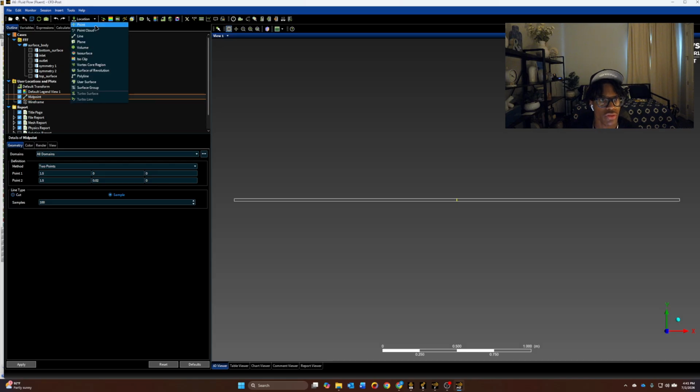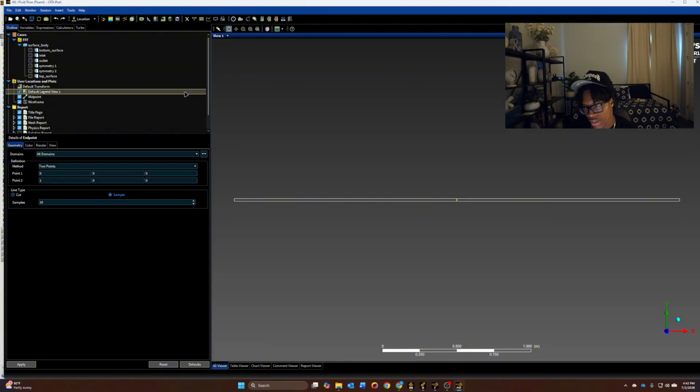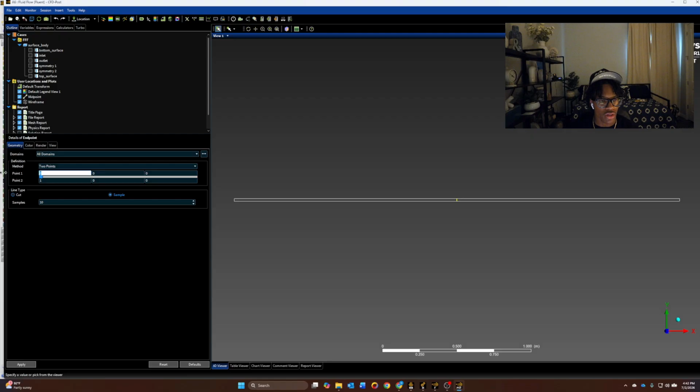We're going to do it again for the endpoint. Now for the endpoint, it's a little bit different. For simulation purposes, the velocity profile doesn't like when you actually have the endpoint all the way at the end. So we're not going to put 3000 millimeters. What I did was I subtracted 1 or 2. So for this sake, we'll do 2, and we'll make it into meters. So it'd be 2,998 millimeters, but we're in meters.